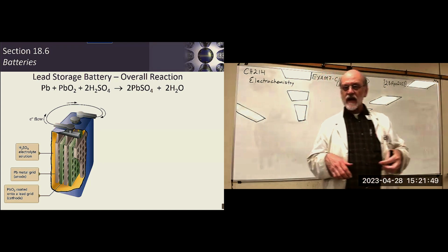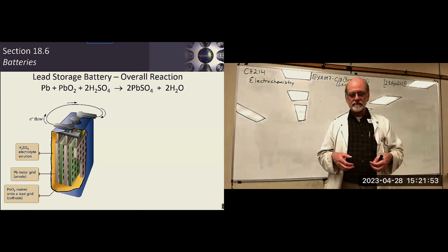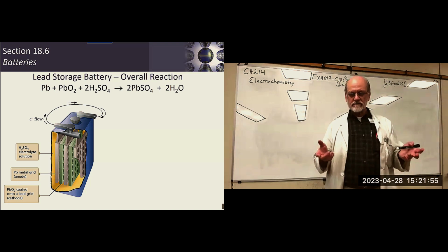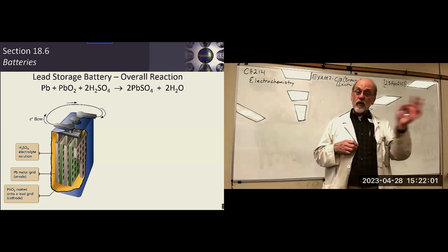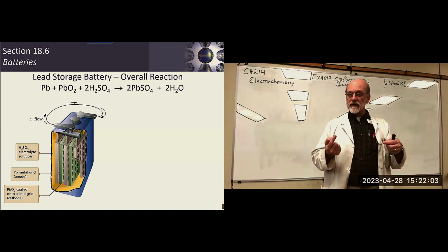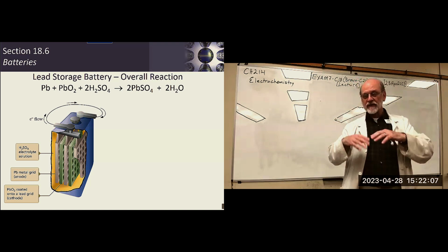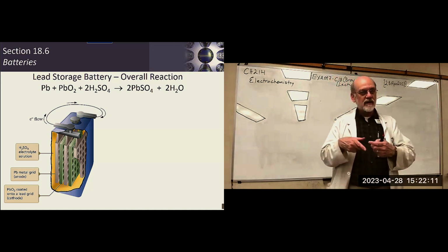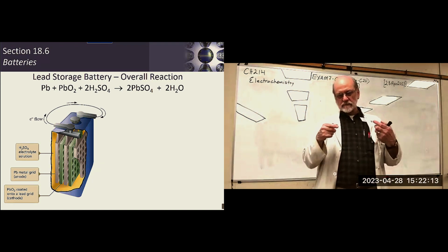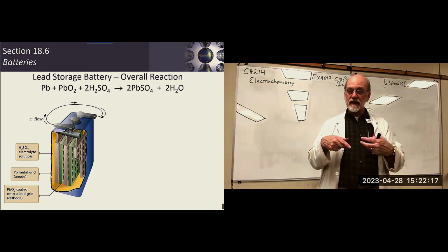But now with technology, they're able to seal the batteries, and you don't have to worry about that escape of hydrogen. Before, with that little hole, sometimes the fluid level in the battery would drop as you converted water into hydrogen and oxygen gas. Then you would have to check your fluid periodically and replenish it.